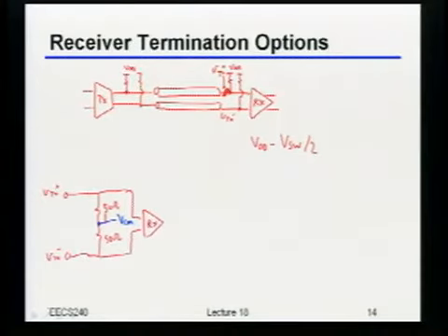And in fact, if you remember, since that transmitter inside of there, that little OTA box that I drew, is really just a diff pair, right? If I did what's drawn with the blue right here, then I'd have a diff pair driving a resistive divider, with that resistive divider setting you at roughly VDD over 2. So the diff pair probably is not going to be too happy, right? The devices might come out of saturation.